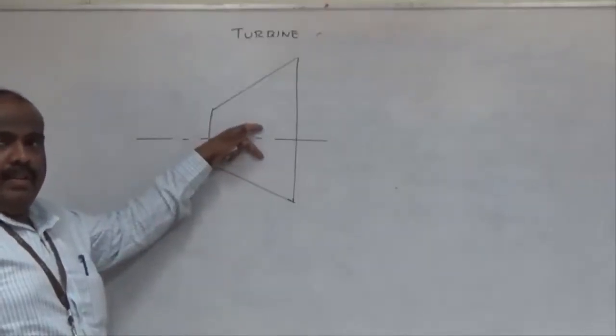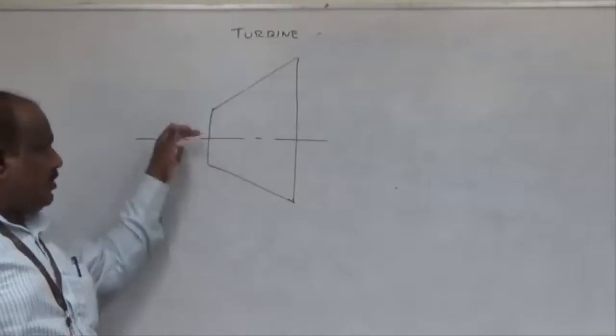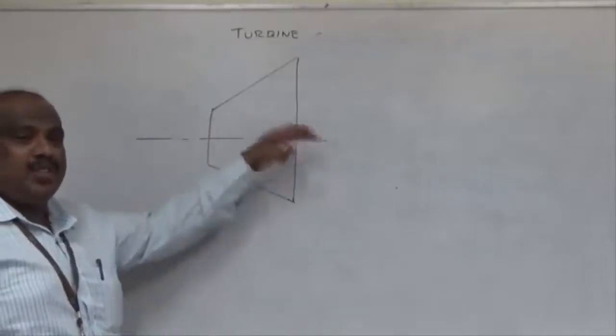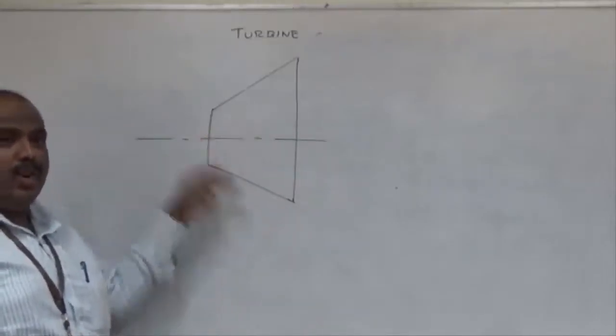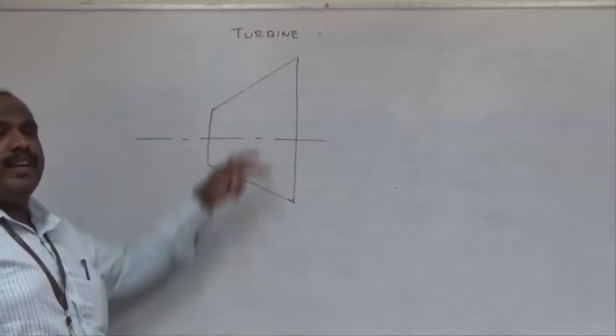It will increase the pressure, sir? It will not increase the pressure. Here the pressure will drop. Only in the diffuser will it increase the pressure. But here the pressure should drop, the fluid should expand, then only it can produce power.